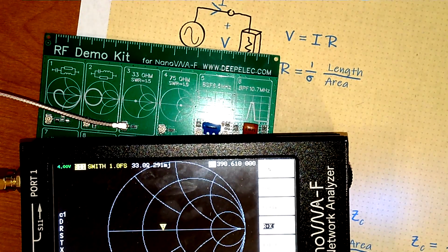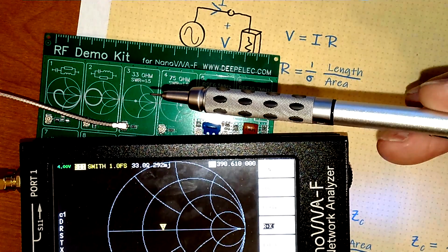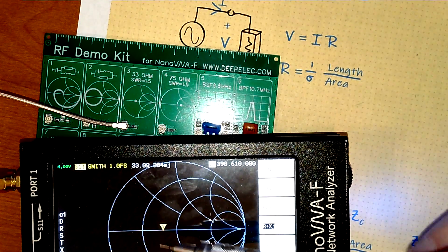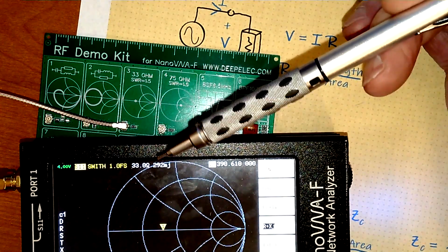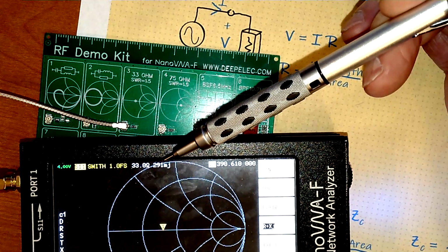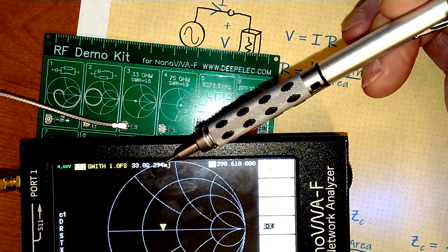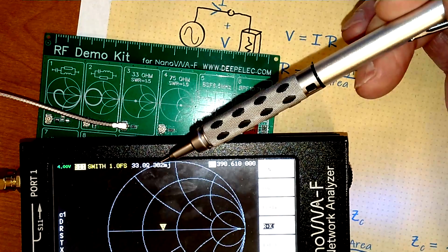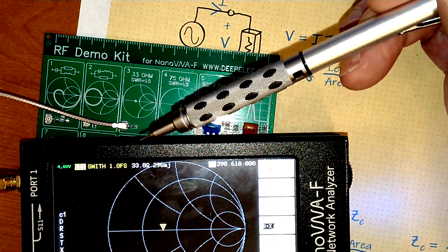This is using the RF demo board, and the readout is now right here. This is a 33 ohm resistor. I don't have a 22 on this demo board. It's a 33 ohm resistor, but we do not have the arc that we had before. We don't have the series inductance. There's an itsy bitsy tiny amount of series reactance here, 0.29, 290 something milliohms of reactance, but compared to 33 ohms, that's insignificant. So it's basically a good 33 ohm resistor because it's surface mount.